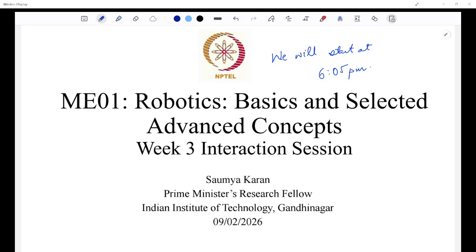We get a compact matrix form when we use the DH convention. Once we have that, we can directly plug in the values of the thetas, phis, or whatever, and get the answers directly. This matrix just has to be put in MATLAB, and you put in the values and you get the transformation matrices.